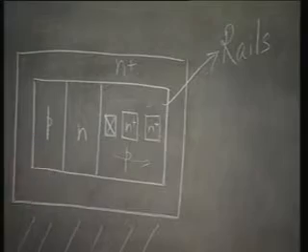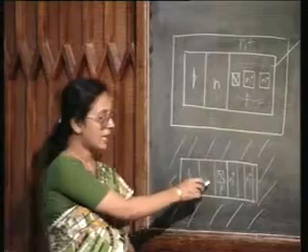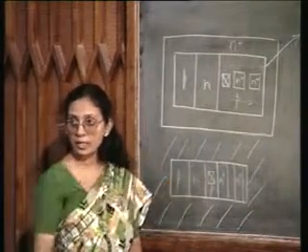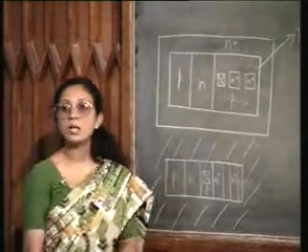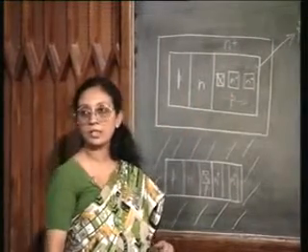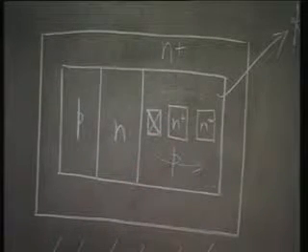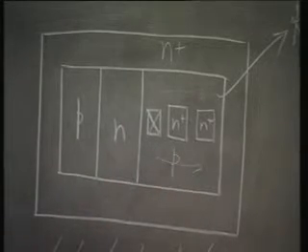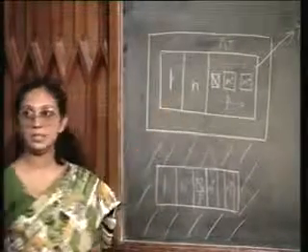So, as is obvious, if you compare these two mask designs, I have a lot of space saving if we use an oxide isolation. Just compare this with this. I can achieve the same using a much smaller region. See, finally everything is determined by your lithographic limitation. So, it depends on how small an N plus region you can have. Here you must have a separation. Here you do not need to have a separation. Therefore, the dimensions of this can be much smaller than in this case.